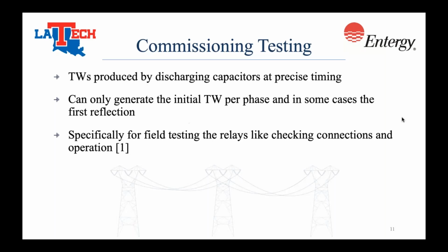This is basically just testing that the relays are hooked up correctly, working as intended, and running the most up-to-date software. Traveling wave testing with injection test sets can be difficult because they have a limited bandwidth. This method is also limited by the nature and number of capacitors. They can deliver only a limited number of traveling waves, and only no or one reflection can be considered.